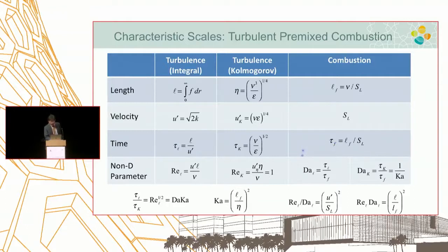And the Damkohler number I define, so we are now introducing the turbulent Damkohler number, is defined by the ratio, same thing, flow time versus flame time. What flow time? There are multiple different flow times all the way from integral to Kolmogorov. So we pick the integral time. That is the original integral scale Damkohler number definition. Well, I don't have to do that, of course.